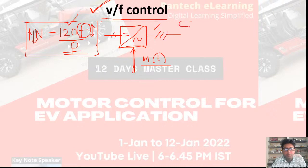But we know flux is another important parameter for the machine, which is nothing but the ratio of V by F, V and F. So now to change the RPM, to increase the RPM, if I increase the frequency, then my flux will go down. To reduce the RPM, if I reduce the frequency, then my flux will increase.